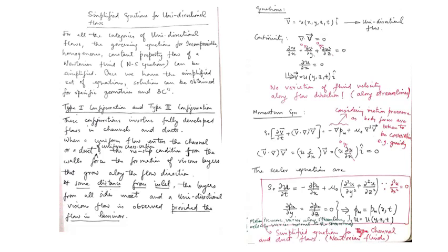Now let's start examining what the momentum equations can give us. We have the momentum equations written in terms of motion pressure. Why motion pressure? Because in carrying out general analysis for unidirectional flows, it is more beneficial to combine the body force, which can only be done if the body force is conservative.